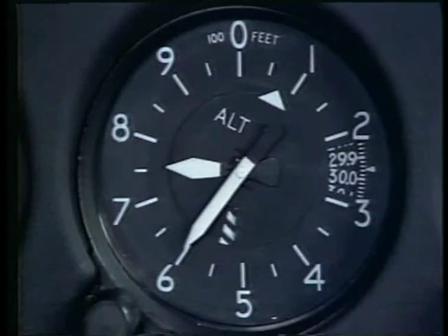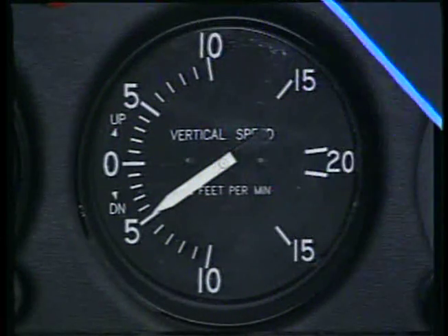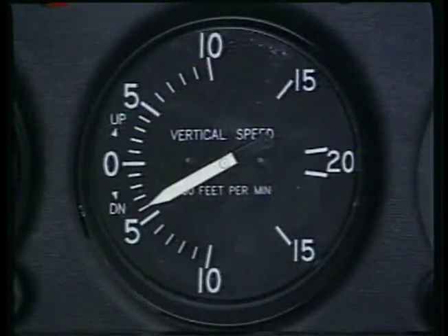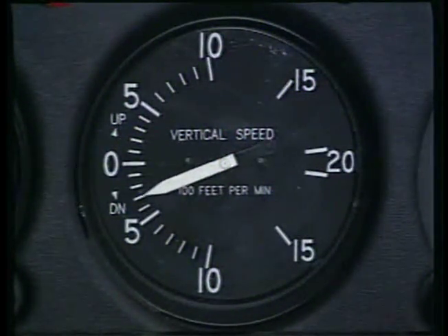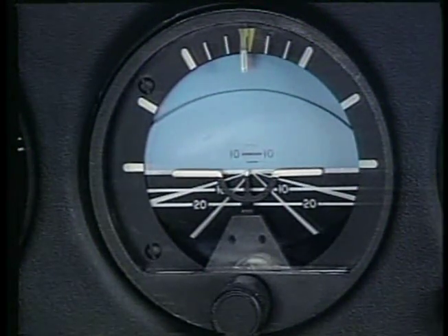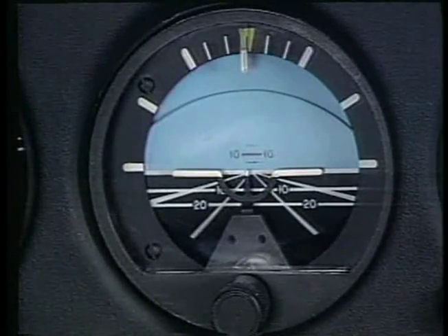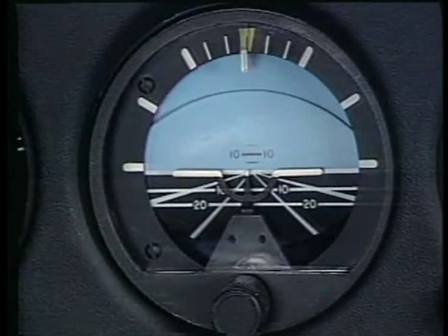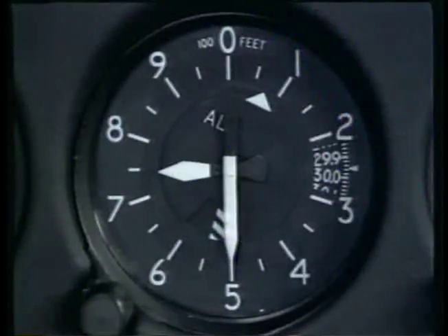As you approach your planned altitude, begin the level off by leading the altitude by about 10% of the vertical speed. Raise the pitch attitude to level flight. Then increase the power while maintaining directional control. When stabilized in cruise, retrim the airplane.